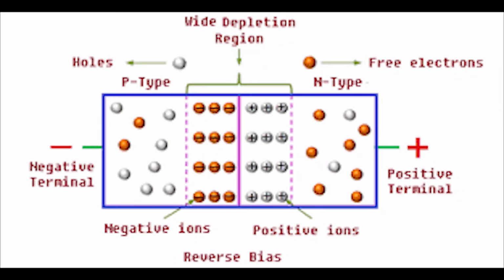Definition of reverse bias. Reverse bias is the applied DC voltage that prevents or greatly reduces current flow in a diode, transistor, and the like. For example, a negligible current will flow through a diode when its cathode is made more positive than its anode. The diode is then said to be reverse biased.